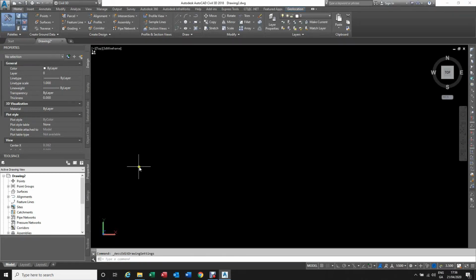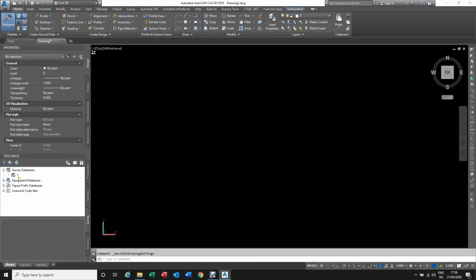So this time I will work backward, so I'm not filling up the survey database as last time. I will bring in a point cloud, I will make the drawing, and then after I can select from the drawing the data and I can fill up the database from the drawing.